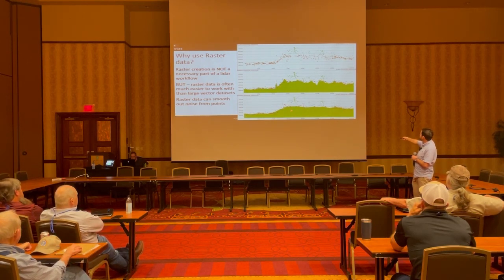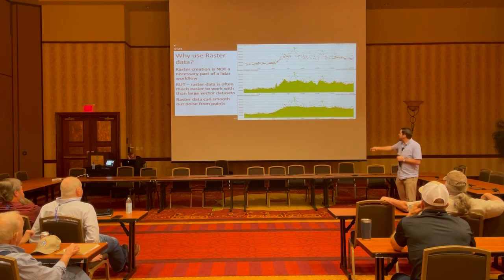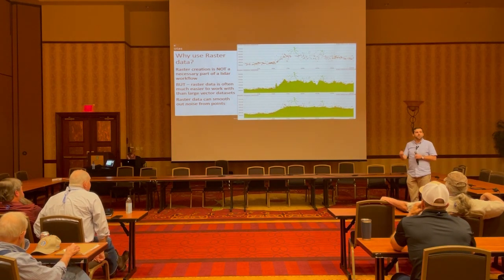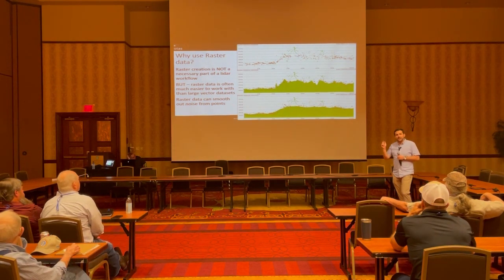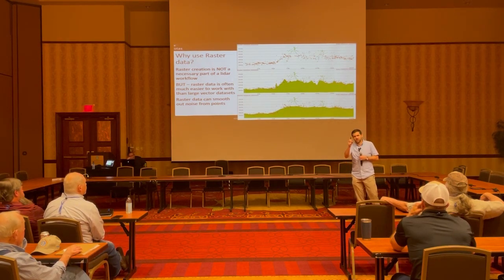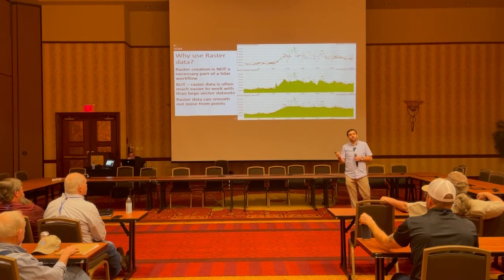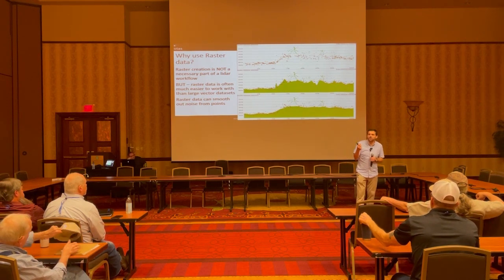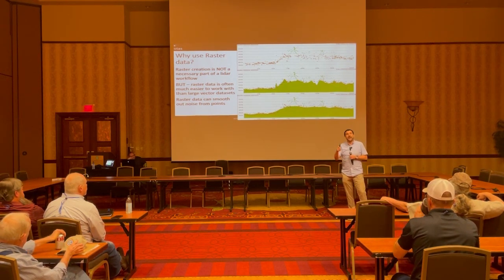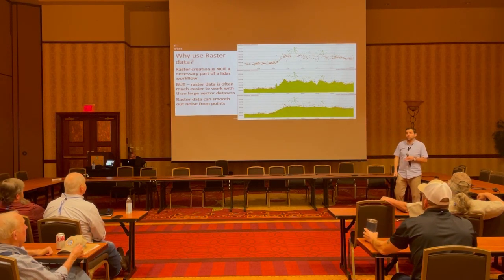When you actually dial in your settings right, you have that much smoother surface. And like I mentioned, that smooth surface is going to be way more accurate than any one LiDAR point. When processing LiDAR, you shouldn't just extract individual points, even with photogrammetry, I believe. It's not great to extract individual points because those individual points aren't super reliable, or at least not as reliable as when you rasterize data like this and create a smoother surface.